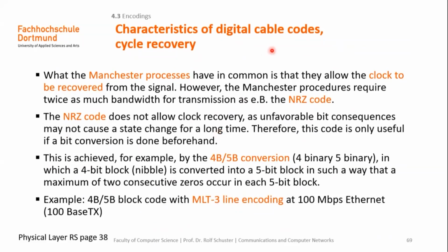Characteristics of digital line codes, clock recovery. What the Manchester procedures have in common is that they allow the clock to be recovered from the signal. However, the Manchester procedures require twice as much bandwidth for transmission as, for example, the NRZ code.